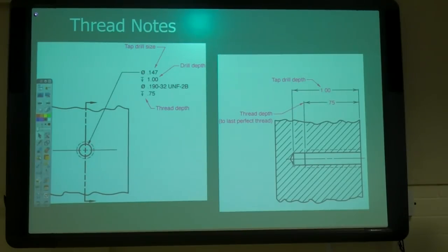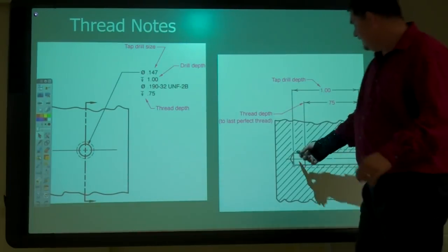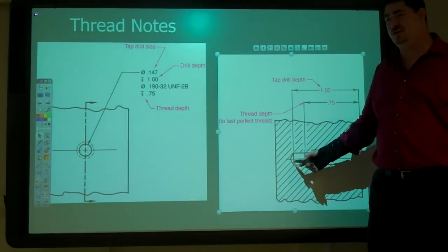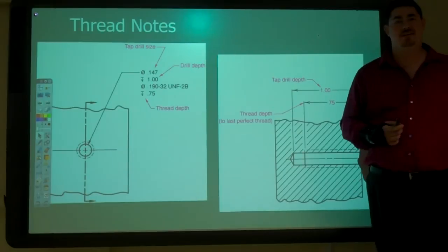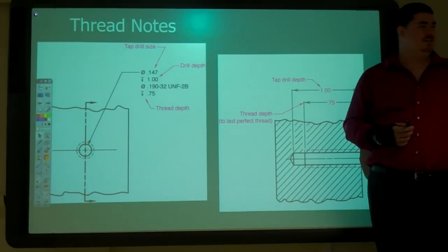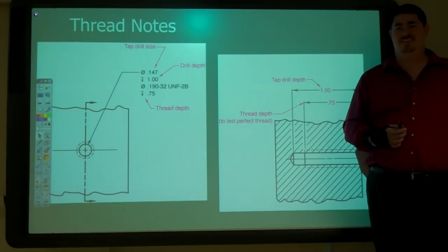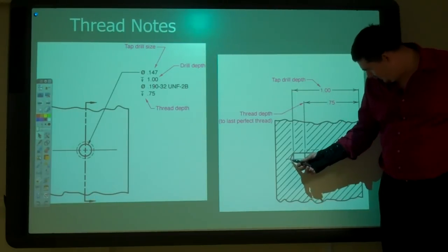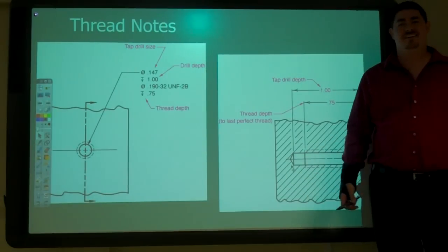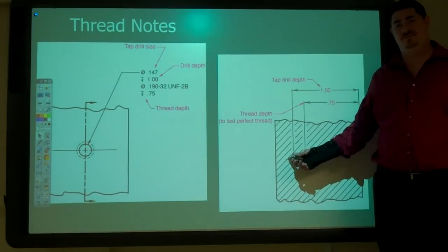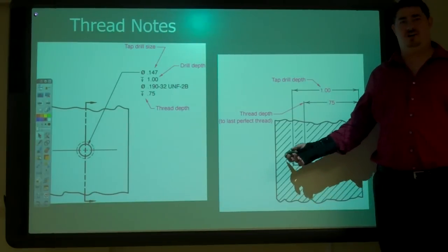Do you want to figure it out? Show you the angle of the drill. Okay, what's the angle? What's this included angle between those two lines? Come on, it's easy. What? 45? Really? That's a 45-degree angle from that line to that line? It's 120, actually 118. We just draw 120.